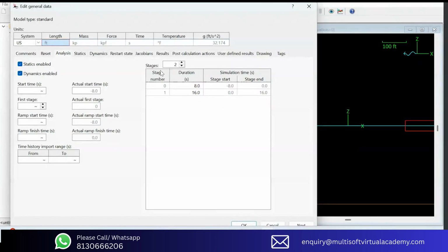So here on the right side, I think you already mentioned the stage numbering earlier when we were discussing the simulation. OrcaFlex always has one ramping stage, and then we have different stages. It's similar to when we were discussing that when a wave or an environment is applied on a system. OrcaFlex is a numerical software, so sometimes if you apply a very high load on a system, there is a chance that it may become numerically unstable.